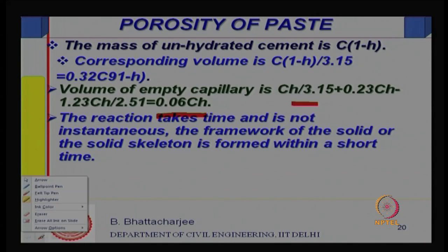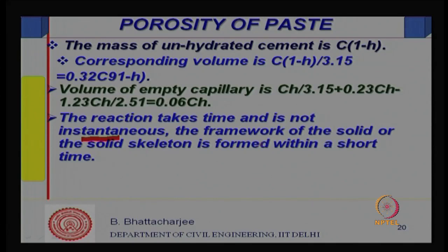Now, reaction takes place over time, it is not instantaneous, but the framework of the solid is formed quite quickly. Within half an hour, the initial set occurs. The framework forms pretty quickly and you can't disturb it any further.